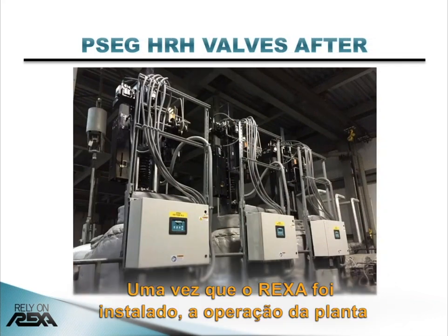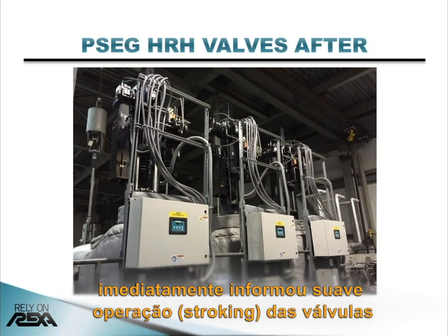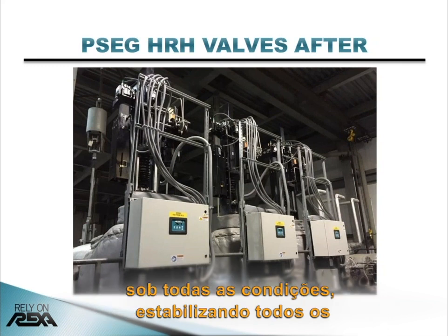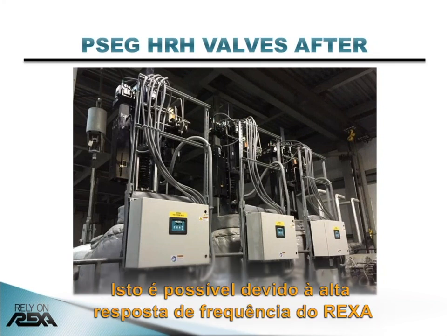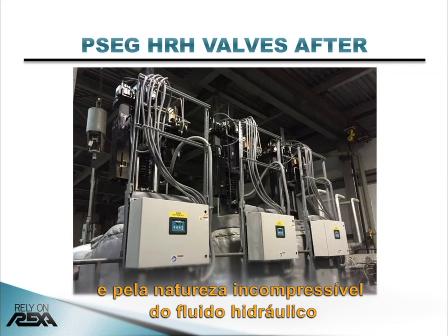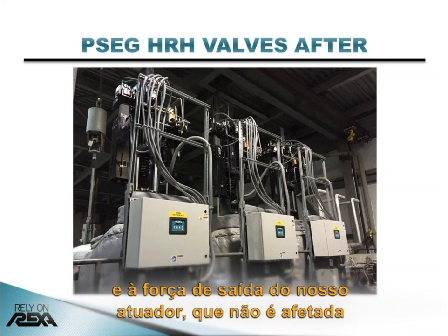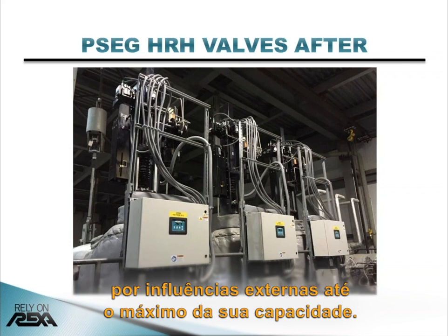Once the REXAs were installed, plant operations immediately noticed smooth stroking of the valves under all conditions, settling down all related equipment. This is due to the REXA high frequency response, the incompressible nature of hydraulic fluid, and our actuator thrust output unaffected by outside influence up to max rating.